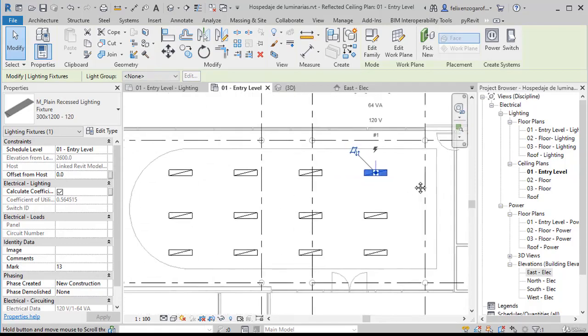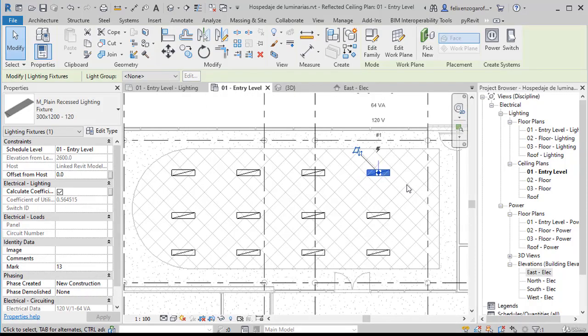A good practice is to talk to the original architect and tell him that, as far as possible, it's best not to create new ones, but to edit existing ones if possible. Sometimes the family changes so much that it is best to delete it and start again. But in that case, it is good to receive a notification, something that can help us, especially in the early stages of the project. Because in the early stages, the ceiling heights and their shapes and configuration change so much.